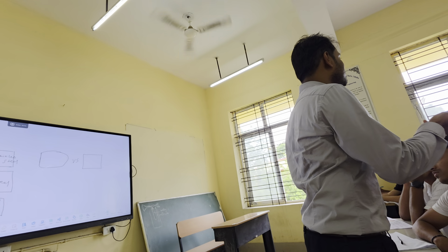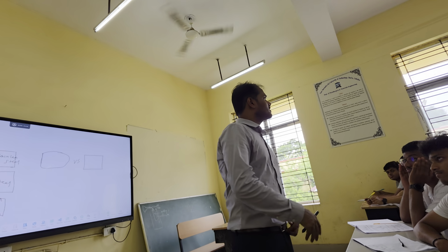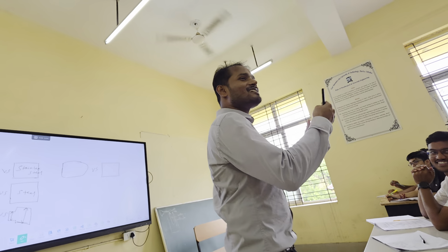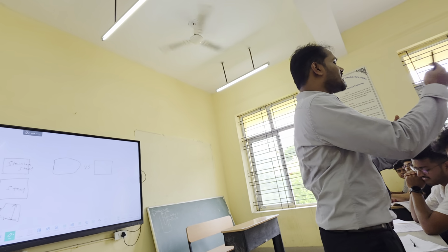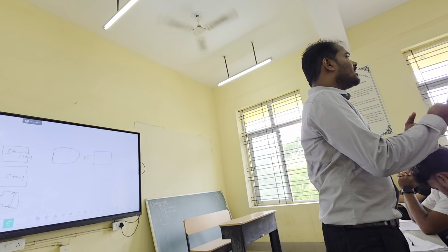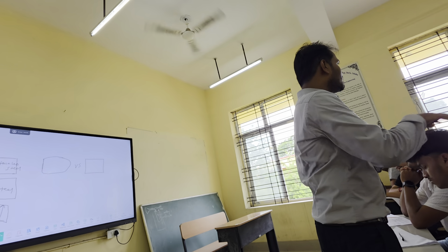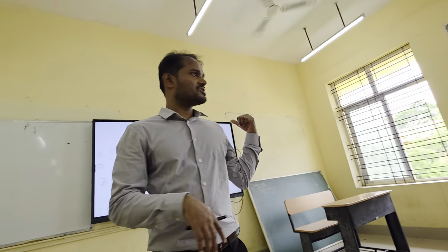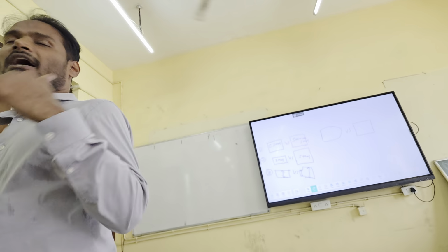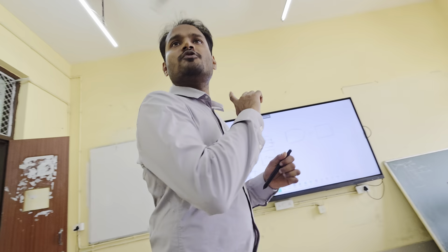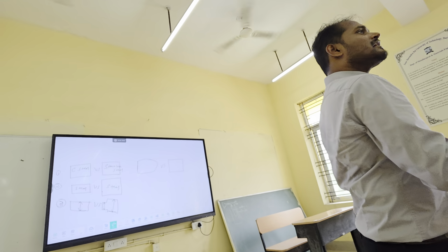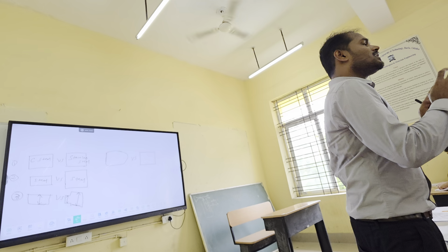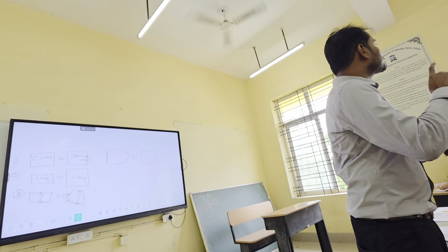Which kind of solid solution is it? Interstitial? Substitutional, because sizes are nearly the same. Size of nickel, size of chromium, size of iron are nearly same. They will occupy the main lattice point, not the interstitial site. Carbon in steel is an interstitial alloying element. Fine. Is it okay? So basically that means in case of stainless steel, heating rate should be slow. But in case of plain carbon steel, heating rate should be high.